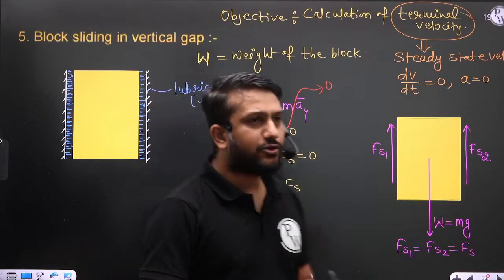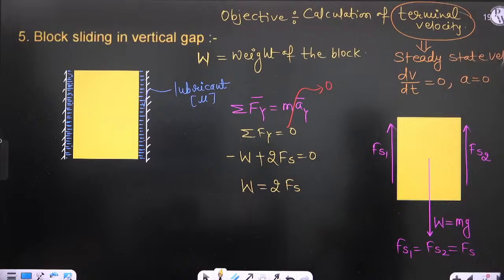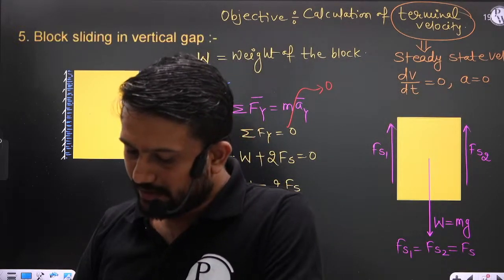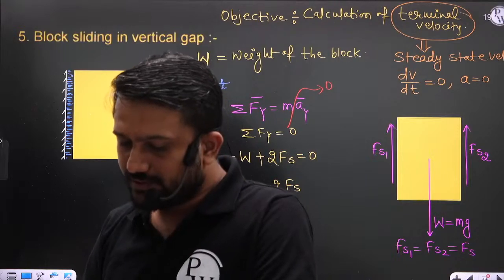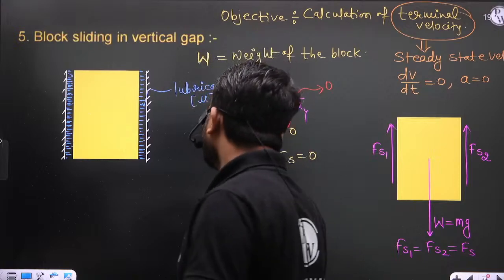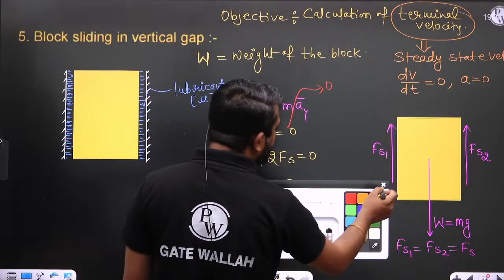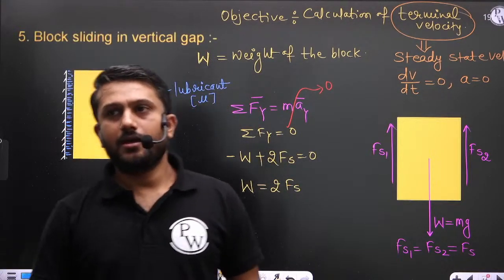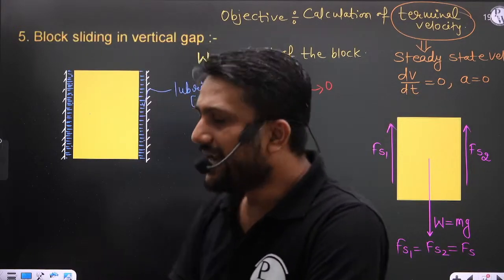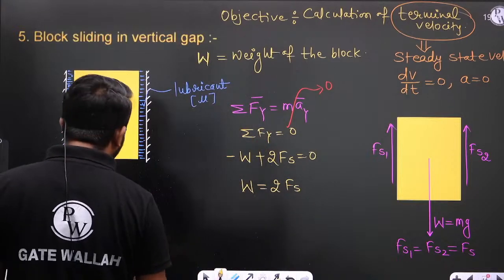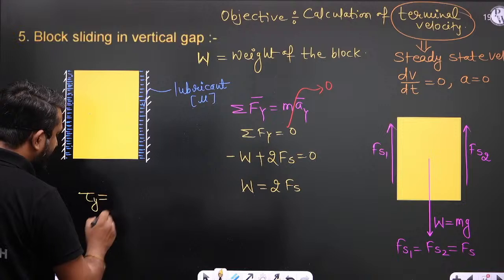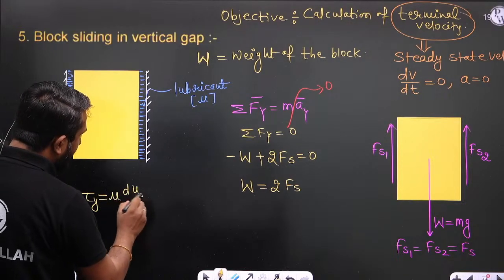Now tell me guys, are you able to find out the shear force? For the calculation of the shear force, we have Newton's law of viscosity. As per Newton's law of viscosity, we know that the shear stress experienced by any layer is equal to mu du by dy.